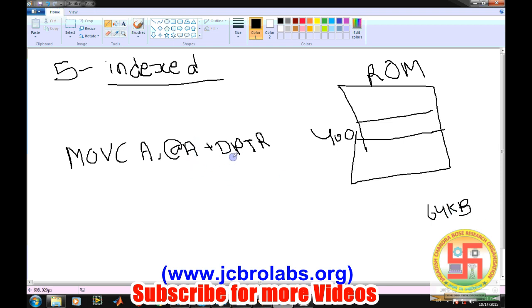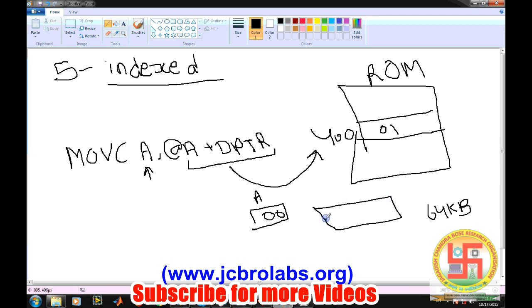So it says whatever the content of the DPTR, add to that the content of the accumulator, and the resulting address is the memory location. Whatever the content is there, move that content into the accumulator. So say we have an accumulator with 00, and DPTR contains 400.